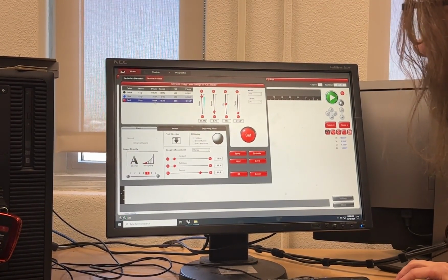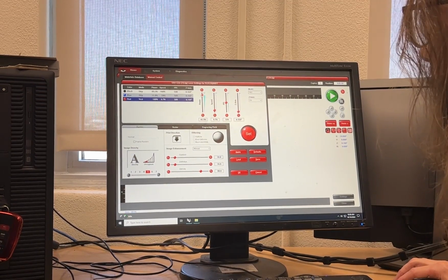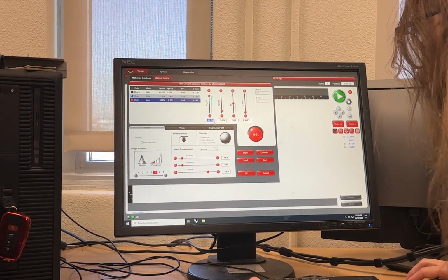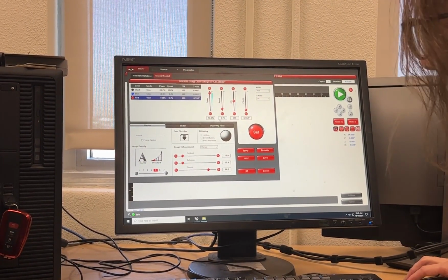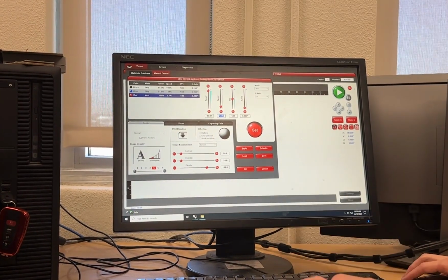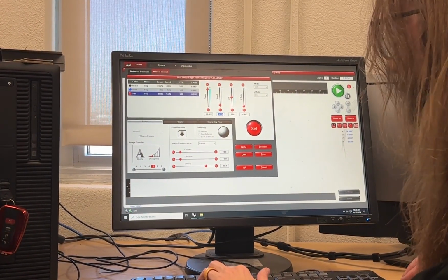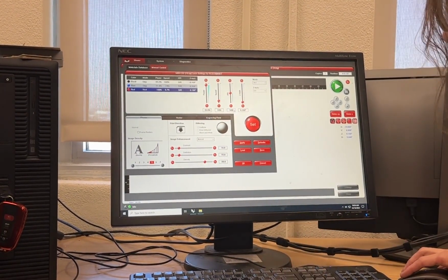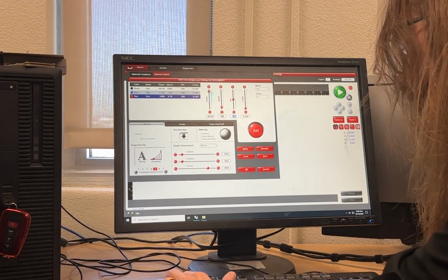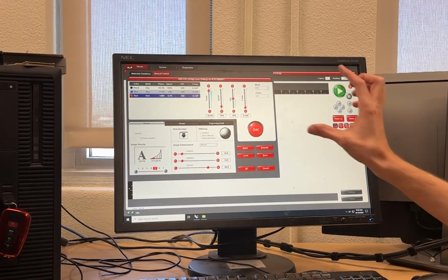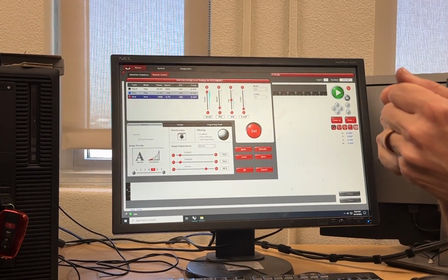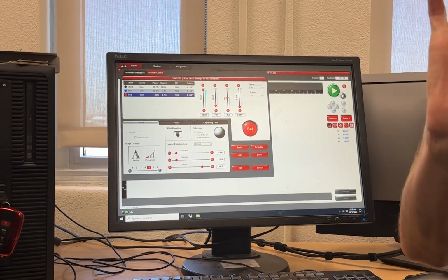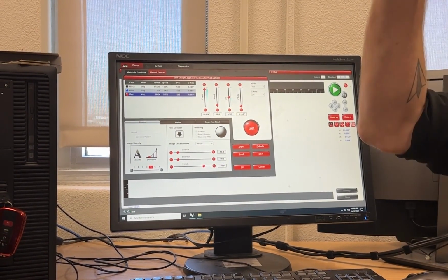But we'll turn it down just a little bit. So maybe, I don't know, 90%. And I can always just type it in too. The speed, it was looking like it was going a little too slow actually for me. So I'm gonna go with 10%. The amount of pixels per inch was fine. Usually 500 or 450 is where you wanna be. So I'm gonna go with 450. Keep in mind, the smaller the number, the more of a sort of a tab break that it'll have, right? Keep in mind that it's a bunch of little saws, so technically there's a little bit of material and a little bit of holes.